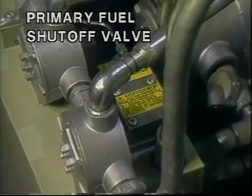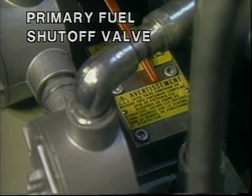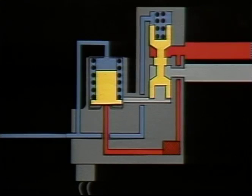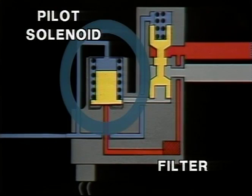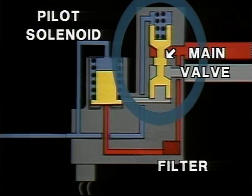The primary fuel shut-off valve is located downstream from the fuel inlet strainer on the fuel manifold. The valve has 3 major components built into it: a pilot gas filter, a normally closed pilot solenoid valve, and the main normally closed spool-type valve.